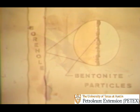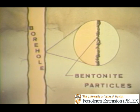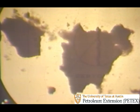The flat bentonite particles, as enlarged in the circle, build up on the wall of the borehole, much like shingles on a roof, and prevent the water phase of the mud from escaping into the formation. Calcium clay does not have the same ability to control filtration. Its structure and size are different from sodium bentonite.